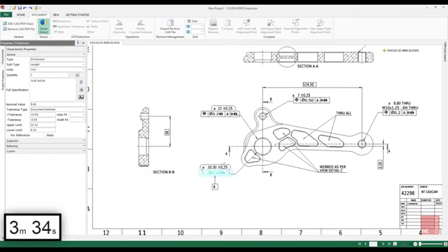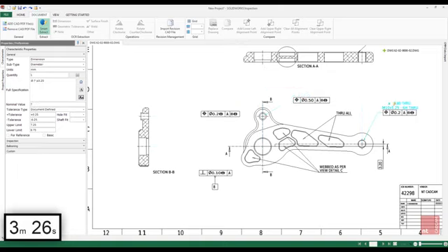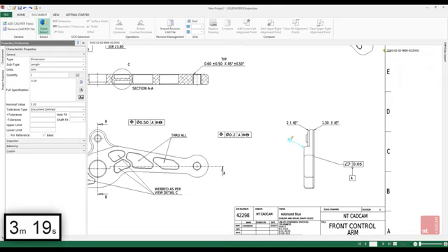We've now started collecting our information. First of all, we're starting off with the inspection dimensions, and then following through into our reference dimensions and our tolerance dimensions. Notice that SOLIDWORKS Inspection understands whether the annotation we're extracting is a diameter or a linear dimension, and automatically fills this in for us.